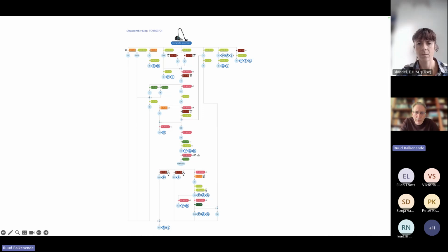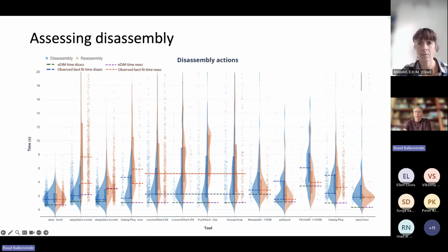And at this point, I would like to make a small sidestep, because many of the scoring systems that I just mentioned use step depth as a measure of the ease of disassembly. So you just count the number of steps that you need to reach a particular component, and that determines the ease of disassembly. But this neglects, of course, the difficulty that some connections might pose. It's therefore a fairly inaccurate way of assessing the ease of disassembly.